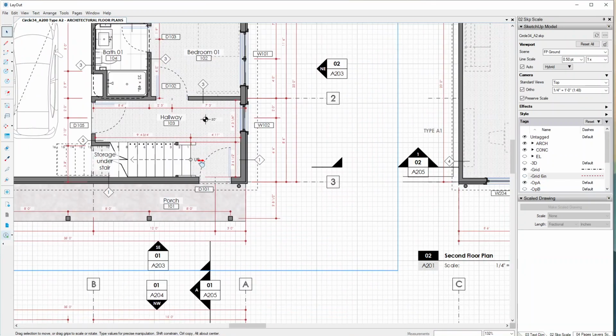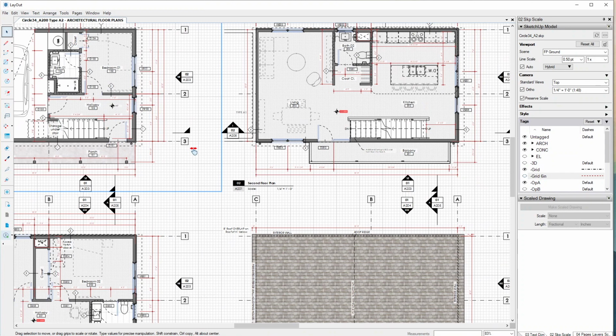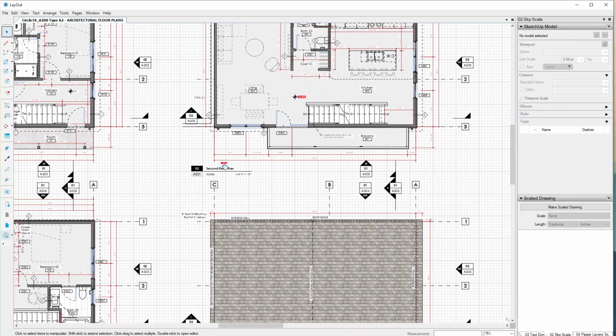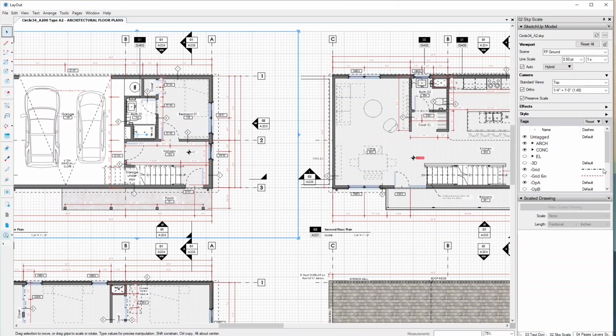Sorry. What else can I tell you about this? There is some line weight set up here. Say for instance, doors and windows are half a point or half of the actual width of the entire viewport. Same for let's say fixtures. Same for furniture. It's 50, but gray, so that it doesn't show that much.